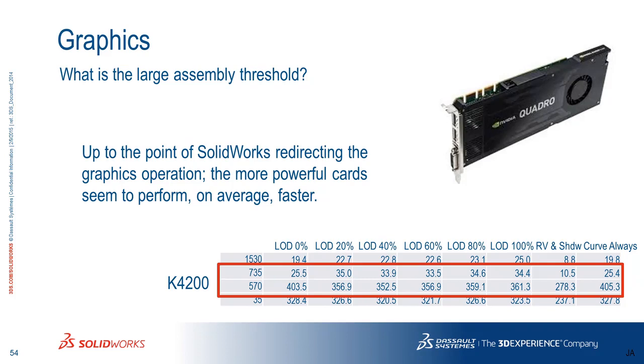That's very interesting, but I can see we've experienced the lag. When you get a big enough assembly, you can click and you can almost watch it happen as it builds it. Turn that off, don't wait for the generator. Your frames per second is a little lower while it rotates. So it's slower rotation or not quite as smooth, but you're not waiting for the bounding boxes to generate and go away when it stops. All right. Thank you very much.